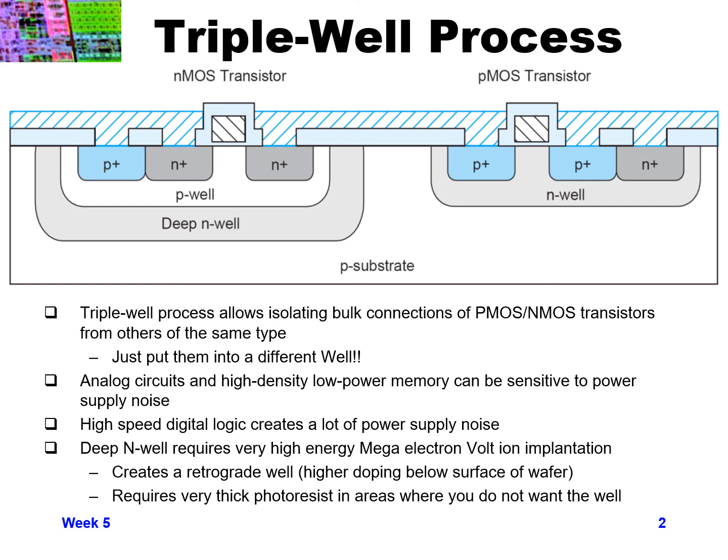On the left-hand side, you can see what we have is our NMOS devices. Instead of the N plus diffusion just being in the P substrate, what we do is we first will basically diffuse a really deep N well as our first step.